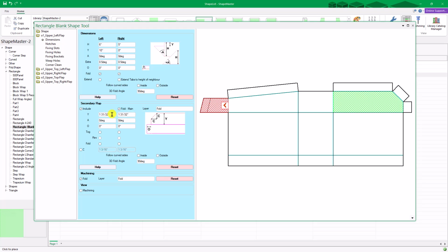Again, you've got full control over this one. So let's go 2 by 3. This will be strange because now it's got an angled fold in the middle, but overall it's parallel. You can specify the angle it wants to fold at. That one goes at 45, that one goes at 45, so between the two they'll actually go at 90 degrees. You have a lot of control over how these parts move.